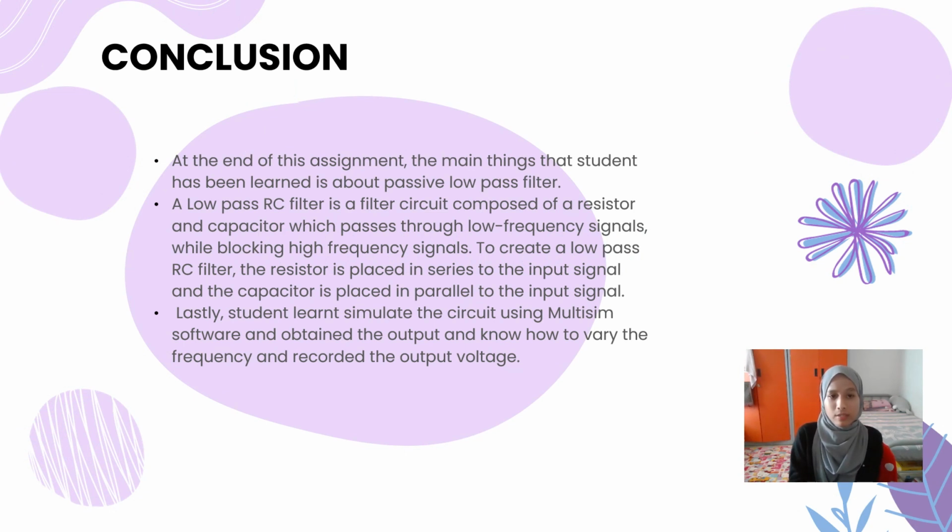At the end of this assignment, the main thing that students have learned is about the passive low-pass filter. A low-pass RC filter is a filter circuit composed of a resistor and capacitor which passes low-frequency signal while blocking high-frequency signal. To create a low-pass RC filter, the resistor is placed in series to the input signal and the capacitor is placed in parallel to the input signal.